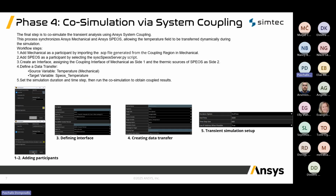Now, the final step is the co-simulation, where we use Ansys System Coupling to connect our thermal and optical analysis. The role of System Coupling is to act as a coordinator and orchestrator. It synchronizes Ansys Mechanical and Ansys SPEOS, allowing the temperature data to be transferred from the thermal simulation over to the optical one as the solution progresses.